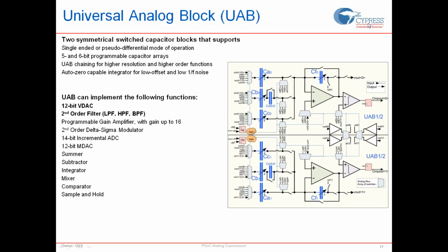On one of the slides you talked about enabling an interrupt on the ADC value. Is this interrupt a one-shot, or does it continuously interrupt when in that window or value? So it is a one-shot interrupt which you have to clear. So once the interrupt is set, it's going to interrupt you, and it's not going to accept any more interrupts on that source. But once you've gone in using your code and cleared that interrupt, you can receive more interrupts based on the source itself.